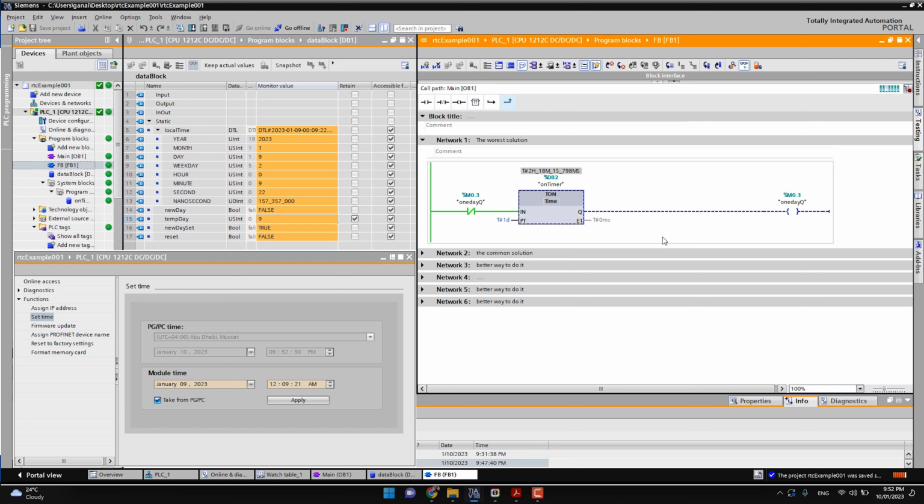And this would impact your data visualization very badly. The second variation of this one I have seen in other sites is using a retentive timer. And again, here we run into another issue, that the timer will count 24-hour operation rather than 24-hour clock.